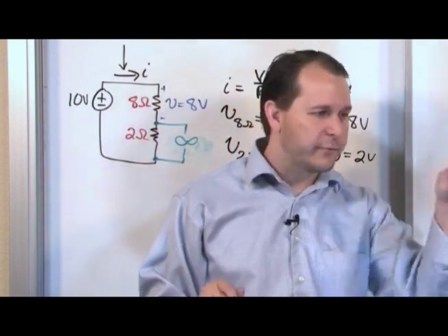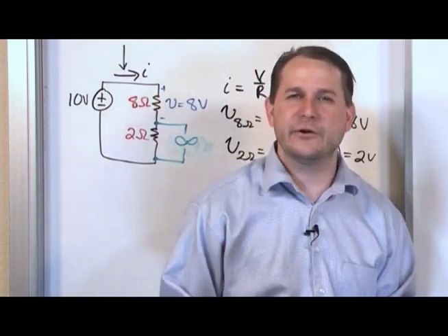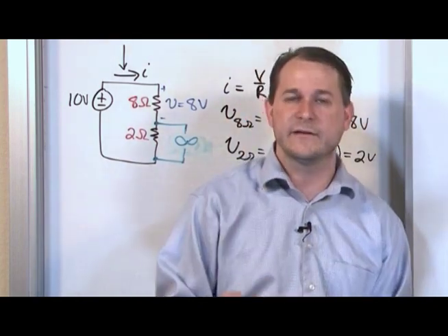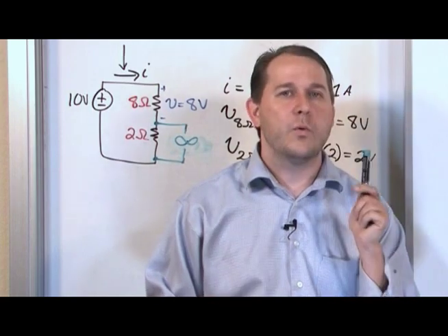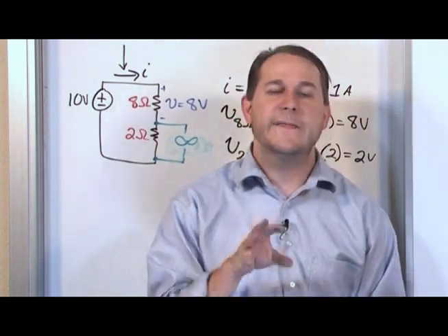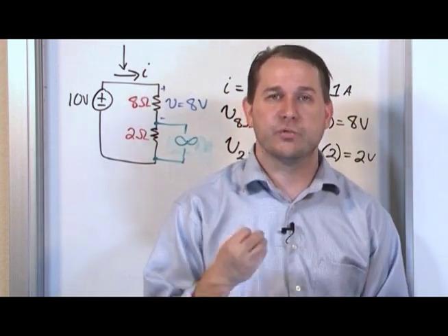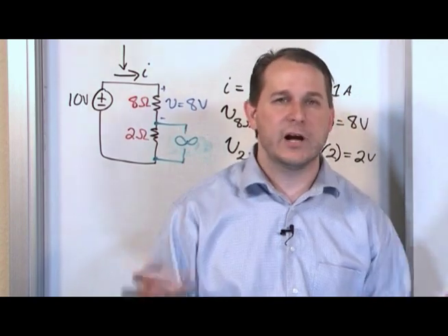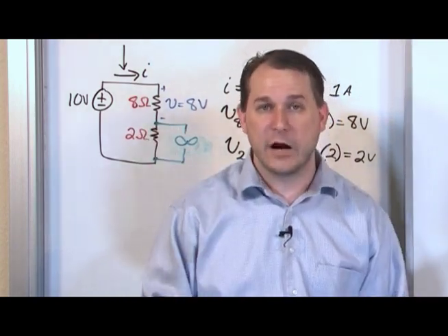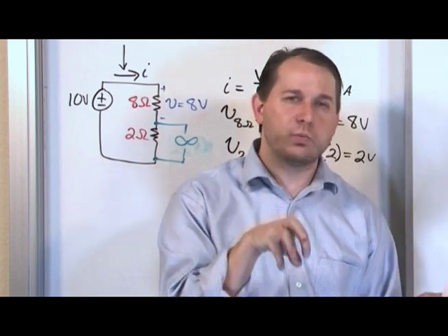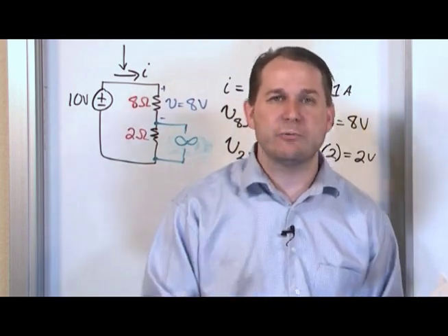When you think about it, you've got resistors. If you hook up a voltmeter, shouldn't it alter the circuit? Shouldn't it change what you're measuring because you're hooking something else into the circuit? That's true, but when they design these voltmeters, they make sure, and here's the punchline, that they have extremely high internal resistance. The way that they pull it off is beyond the scope of what I'm talking about. But when they build voltmeters, they make sure that the internal resistance of that meter is extremely high.